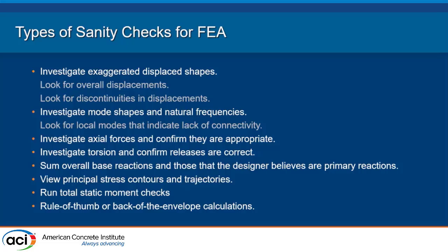You want to investigate the axial forces. I think this is especially important for concrete because there's compatibility of deformations that can create axial forces in your flexural members. It does impact the behavior. Sometimes it's right, sometimes it's wrong relative to how you've modeled it, but you want to understand that it's there.